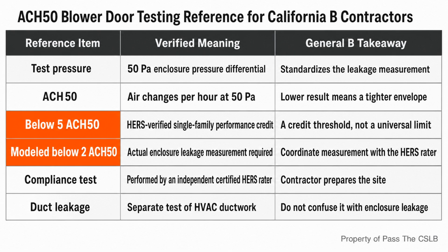When employees are required to use respirators, California occupational safety rules require the employer to establish and implement a written respiratory protection program with procedures specific to the worksite. That means respirator use is not reduced to handing out masks at the door. The program governs matters such as medical evaluation, fit, selection, training, use, and program administration as applicable to the exposure. A simple filtering face piece chosen for nuisance dust is not automatically suitable for spray polyurethane foam chemicals. Respiratory protection has to come from the formal hazard assessment and program, not improvisation by an individual worker.